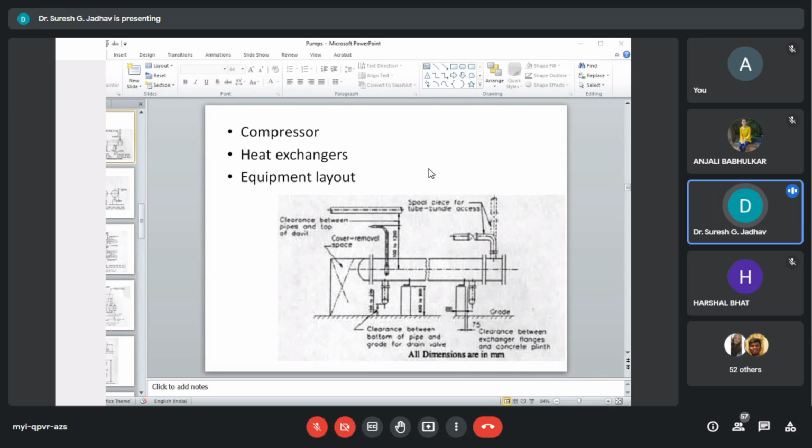Pipelines connecting the exchanger with adjacent process equipment can run point to point just above the required headroom. Steam lines connecting to the header on the rack can be arranged on either side of the exchangers. Valve handles should be made accessible from the ground and from the access way. This access way should be used for arranging manifolds, control valve stations, and instruments.